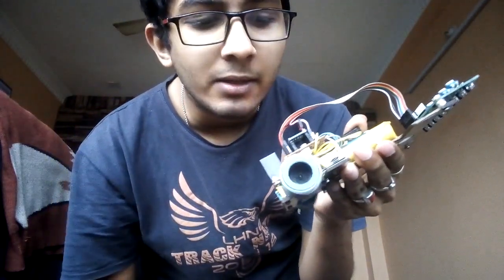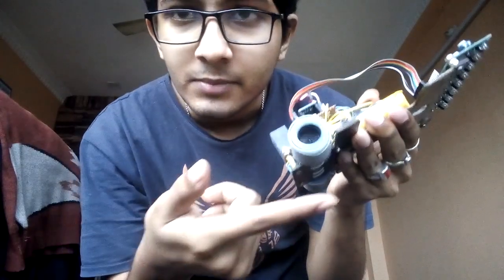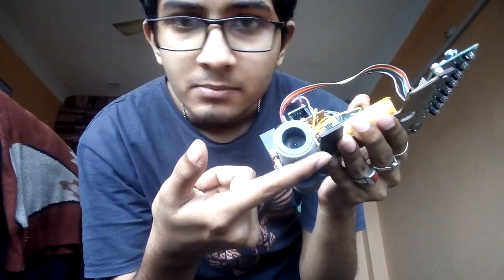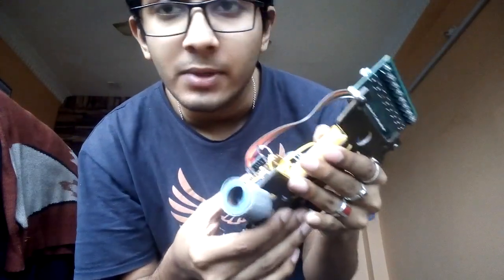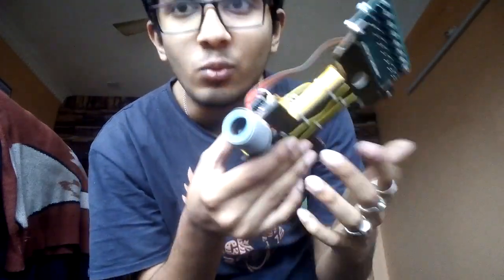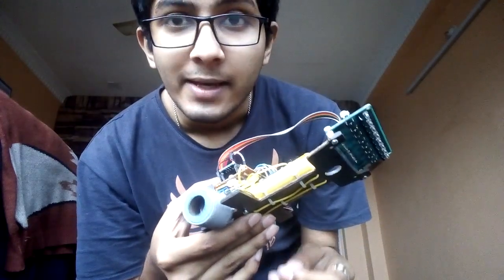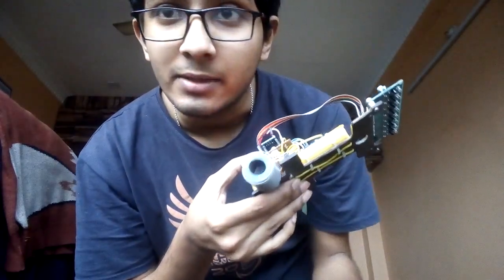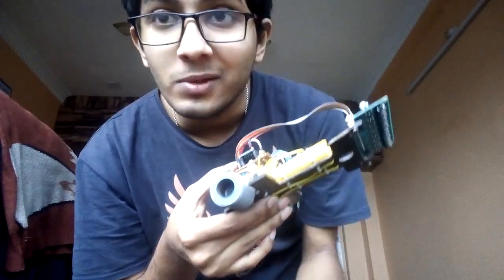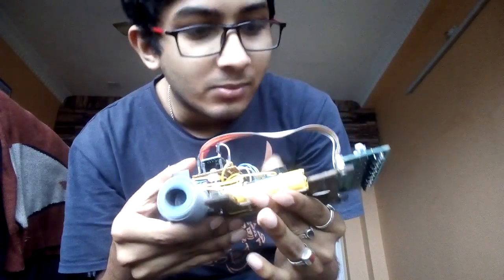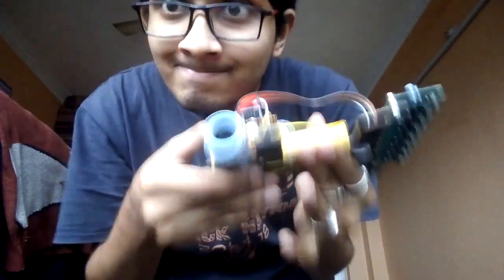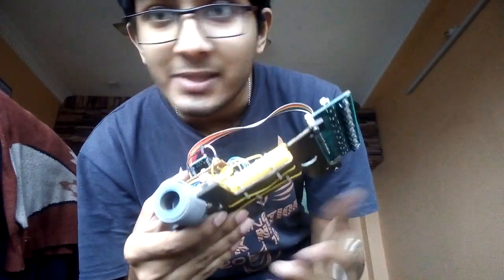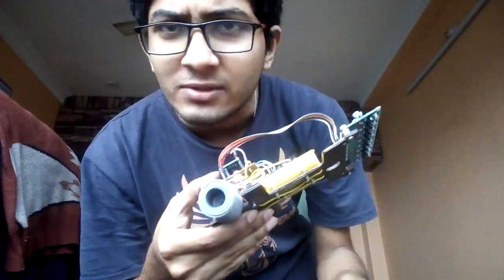To make a proper turn, we have to get rid of this wobbling. As you can see, the whole board jumps like this, and that's why it interferes with the sensors too, because the sensors work at a particular distance from the line, and when this thing wobbles, this whole board is like that, the distance reduces and the sensor malfunctions.